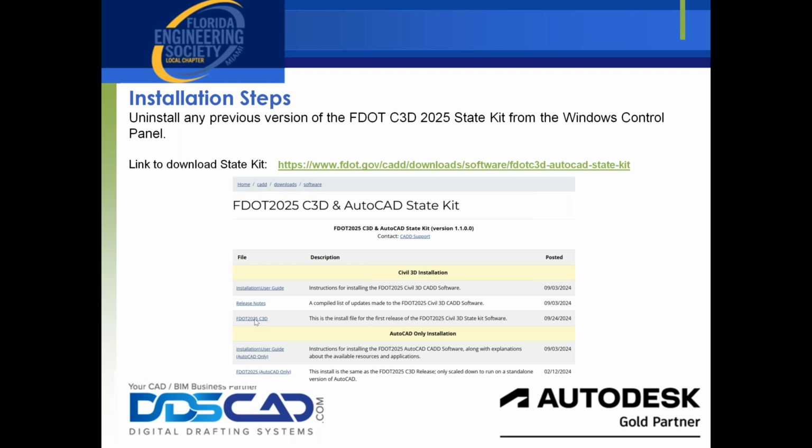That brings up another good point. Sometimes people will go in there, like they have a SURV RD 01 file, and then they'll do a save as and save it as 05. And then the next time they go into the Create File tool and want to create another SURV RD file, they think it's going to be 06. No, it finds the next available file, which in this case, if you only had a 01, would be 02.